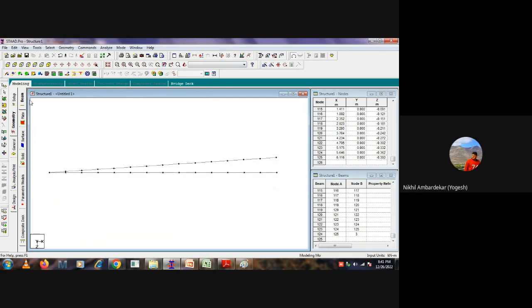So now we have to create plates. Now we don't have any restrictions for the local axis. So take a liberty and you can create plate as per your requirement, but just follow that pattern. If you start from the bottom left corner, you can repeat that same for everyone. You have to create plate for this.